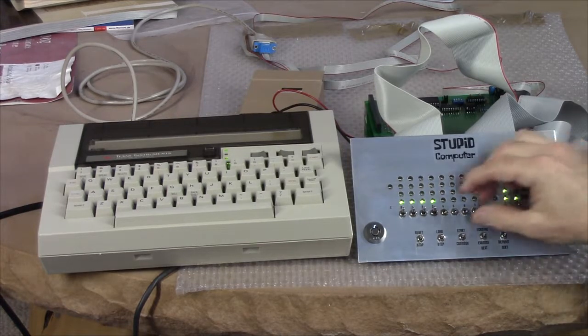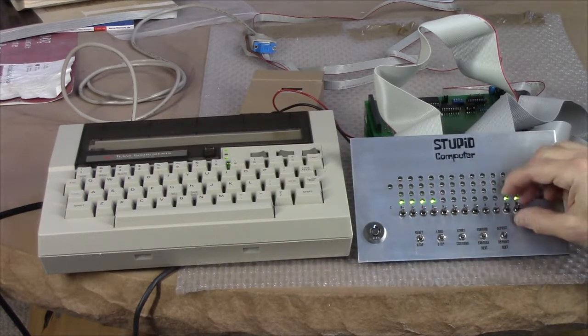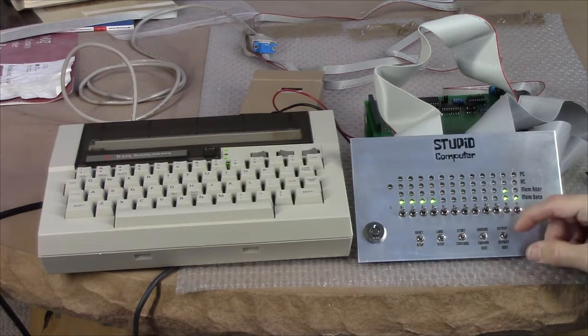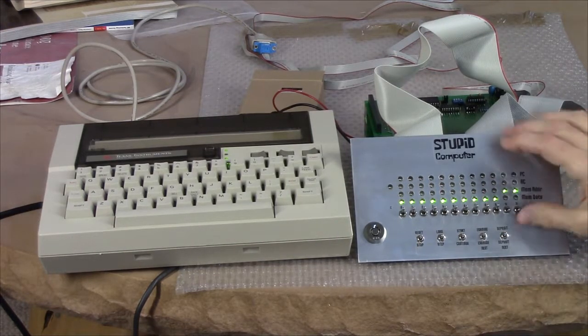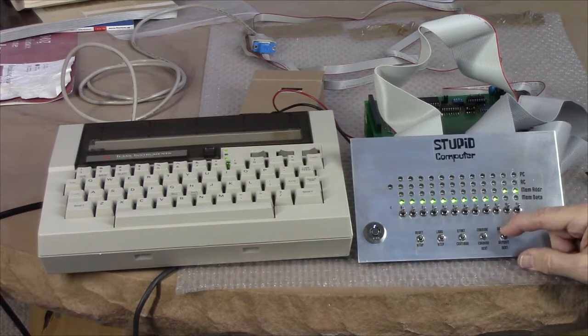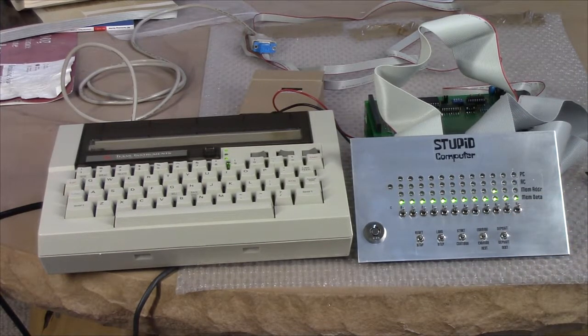To fix it would be difficult. One thing I could do is yank those 670s out. But that board is full that it's on. So if I try to use other registers in there, for instance, 174s, which I use for all the other registers, I wouldn't have enough space.